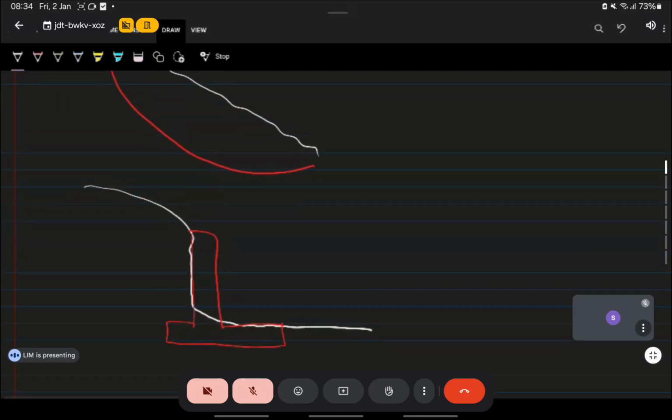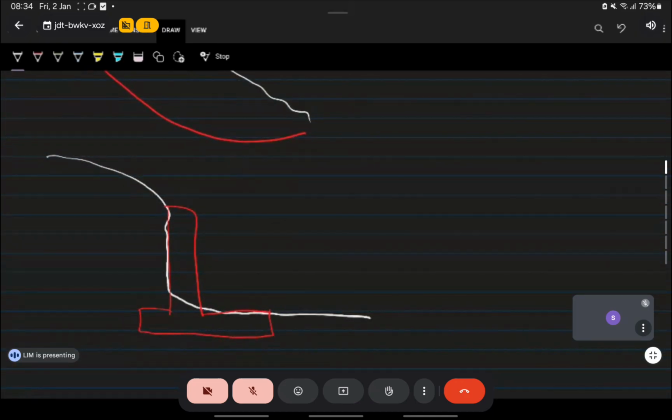So yeah, just some terminology. I just want to share some terminology with you. So concrete retaining wall, normally it's an inverted T like this. Yeah, I call it the inverted T. Yeah, because T is like that. Inverted T is like that lah. Okay, so concrete retaining wall is normally an inverted T. The vertical part is the actual retaining wall. This is the wall, or sometimes we call it the stem. Okay, the bottom we call it the base.